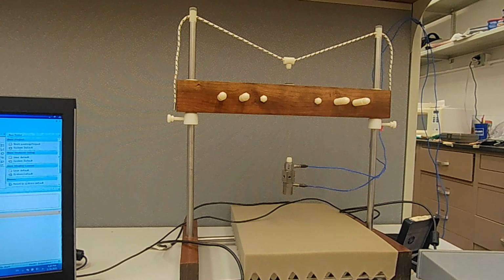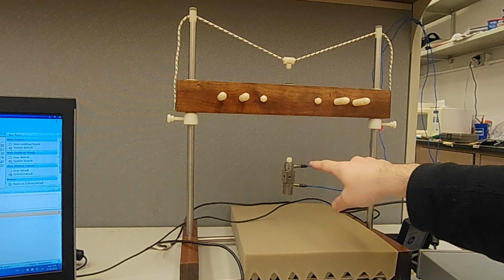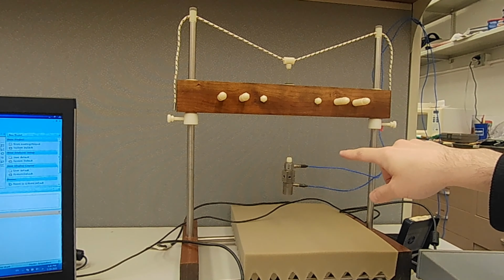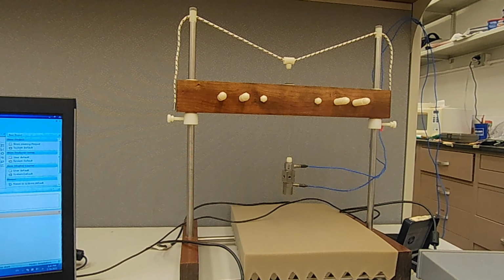All right, so we have an apparatus in front of us, and this is our gravimetric calibrator, and we are going to use this notion of gravimetric freefall calibration in order to identify the sensitivity of our piezoelectric accelerometer. So we have our device suspended from the string here. There is a load cell which we will use for the next part of the experiment. There is a mass which is unknown, and we have a piezoelectric accelerometer down here, and this is what we're going to find the sensitivity for.